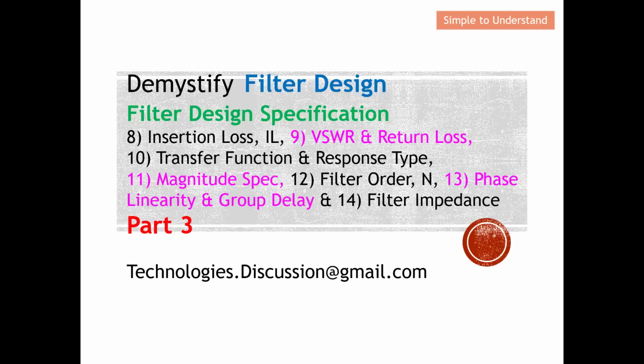Basically, in this video, I will discuss what insertion loss is. Next will be the VSWR, which is also return loss. We have various transfer functions and response types, for example Butterworth and Chebyshev, which I'm going to discuss. On the magnitude spec, in some cases, we allow ripple in the pass band or maybe ripple in the stop band. Basically, this will quantify how much ripple in terms of magnitude is allowed for the filter design.